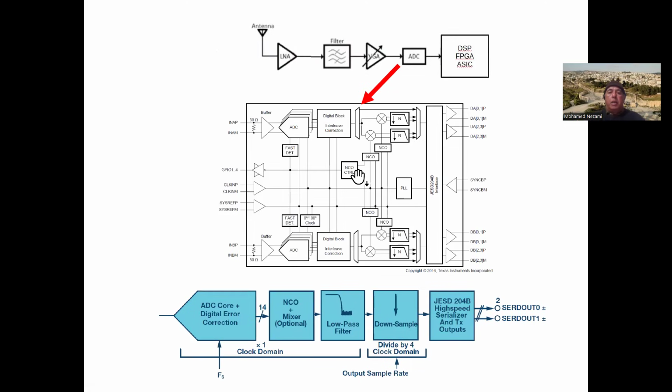So now the ADC, as you can see in here, really isn't just an ADC anymore. It could be two, quad, or even 16 channels. Not only this, but the ADC itself is actually an interleaved ADC, which is a technique to speed up the conversion. We have talked about this a little bit, and we'll talk about it in the coming sessions because there are some impairments due to this technique, which have to do with the interleaver spurs and harmonics.